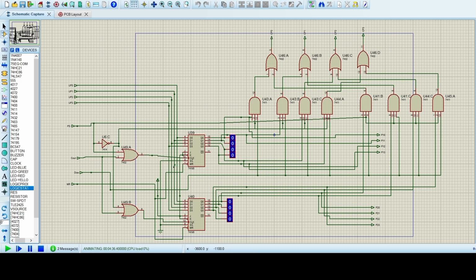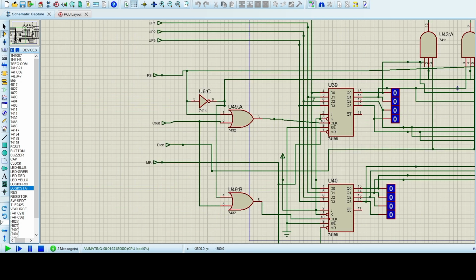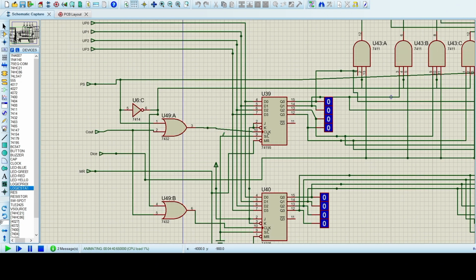Now, after we have seen that, let's see how the registers are updated. First of all, as mentioned previously, the carryout works as the clock, because the carryout only gets 1 after we have calculated the updated value. So we have sent that carryout to the OR gate. Now we have to choose the appropriate player register. Again, the player selector value comes in.